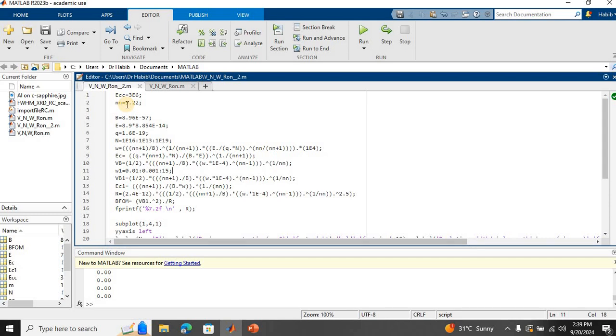As I discussed in one of the slides, I took this value from one of the references which found the fitting parameters N and B. Similarly, this value over here, B, is also a constant related to gallium nitride avalanche breakdown characteristics. It's an empirical constant that defines how breakdown voltage relates to doping concentration and depletion width.